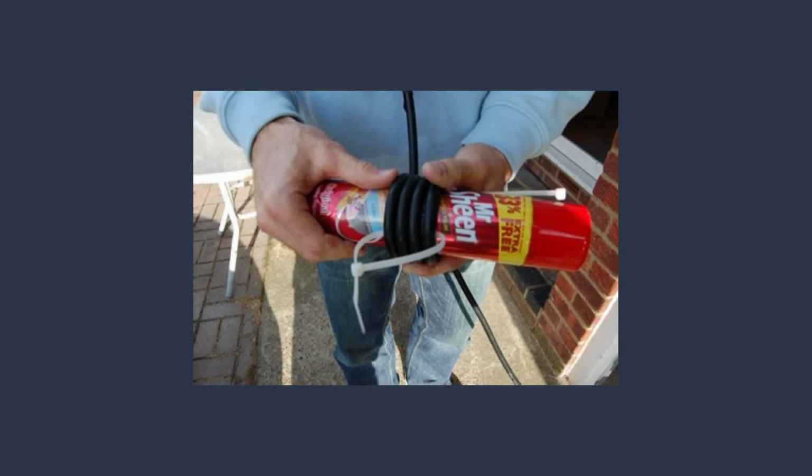Now I'm assuming that in most cases, what I do if I was making an air wound choke, I would use a household can. It may be a Mr Sheen can for somebody in the UK, or for outside of that a WD-40 can, and use some sellotape to hold 3 or 4 long cable ties around the outside of that can, and then I would wrap my coax cable however many turns, 5 or 6 turns around one of those.